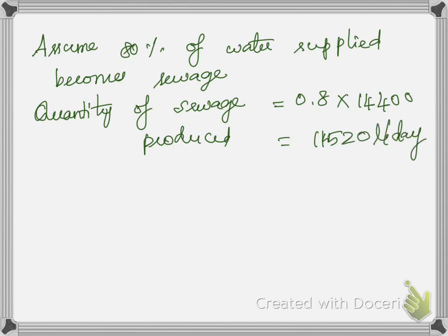So this is your quantity of sewage produced. Now you are going to assume your detention time. Assume your detention time as 24 hours.